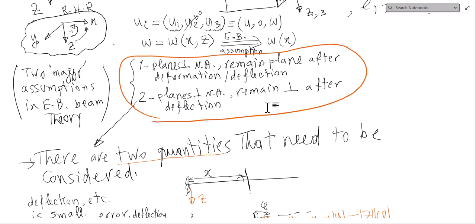If it is less than that, then using Euler beam theory increases the error in deflection, and sometimes it can go up to 50% error, if you apply Euler beam theory to all cases, because it ignores the deformation or deflection due to shear stress, as we showed here.